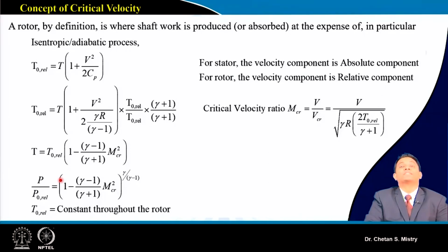So basically we are sizing our compressor in order to achieve the expected pressure rise. Suppose we are not getting it, we do all kinds of modifications in the selection of my pressure ratio, in the modification of my radius ratio, my aspect ratio, so many parameters will come into the picture. Okay, and once you have done all this calculation based on your computational study, you will come up with the verification. It says yes, this is what we expected in terms of my pressure rise.